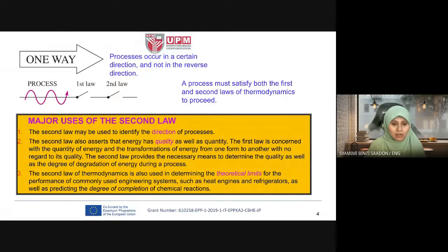The second law also asserts that energy has quality as well as quantity. The first law is concerned with the quantity of energy and the transformation of energy from one form to another with no regard to its quality. The second law provides the necessary means to determine the quality as well. So the point here is quality.